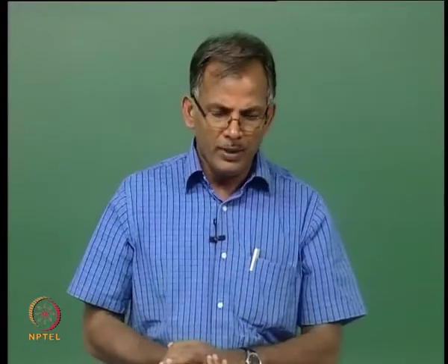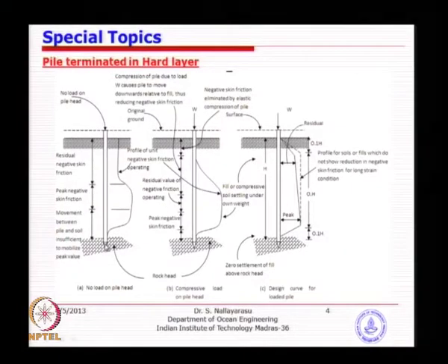So that's why pile type of foundation is not recommended when you have fill soil for the top layer. Also it depends on what is the type of bearing stratum. Suppose you have a very hard bearing stratum, the pile is fixed down there. Imagine if the pile is not fixed to the hard ground, if it is a floating pile, the whole soil layer together with the pile will go down. So the relative movement is not going to be so much of a problem, whereas here the pile is not going down, it is going to take the load and then try to yield at the bottom. So that is the problem.